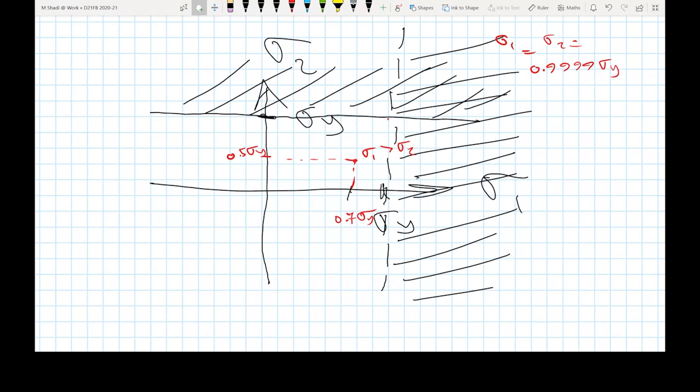Once it crosses sigma y on either this direction or this direction, you get into the case where it has yielded. So the stress has exceeded the yield point. All right. So within this quarter, where you have sigma 1 and sigma 2 both positive, you have this square there. Sorry again for the quality of the drawing. So you have this square. This is an elasticity region. And beyond this square, everything beyond these points is going to be an inelastic region or plastic region.